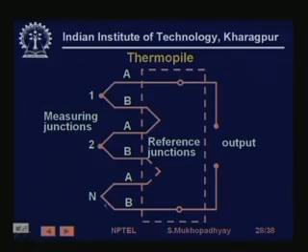Similarly, if you connect many thermocouples in series, you can further increase the sensitivity, and so if you put n number of measuring junctions, then this voltage will be n times the voltage that you can get from a single thermocouple. So, that is called a thermopile.